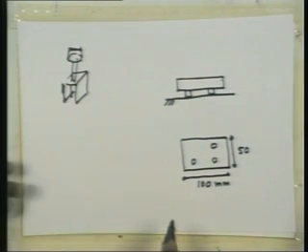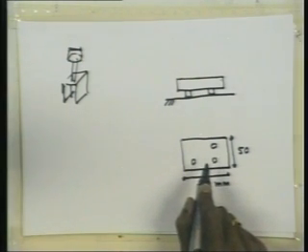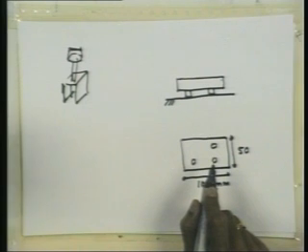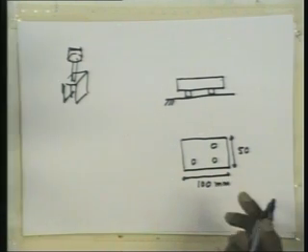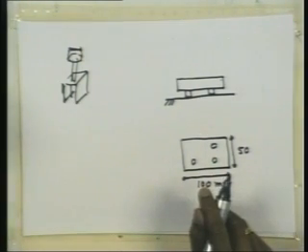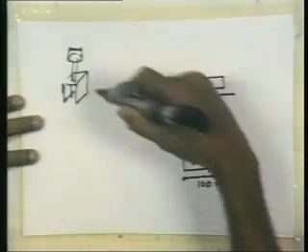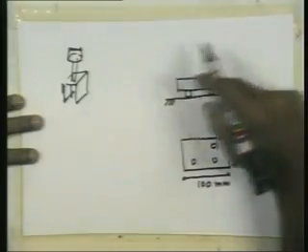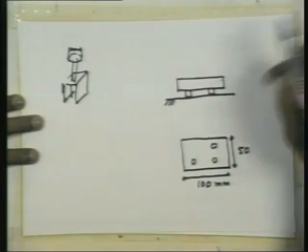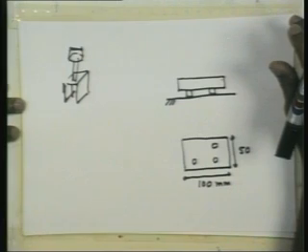Remember, what we need to do is locate these pins, these specs on top of the holes. We need to do that finally, right? So how do you pick it up? There are many ways of doing that. Now think of some simple way. I can pick it up with one of these sides of the gripper touching this and the other on the other side, or touching these two faces, right? If I try to hold by the edges, it will not be firmly held, right?